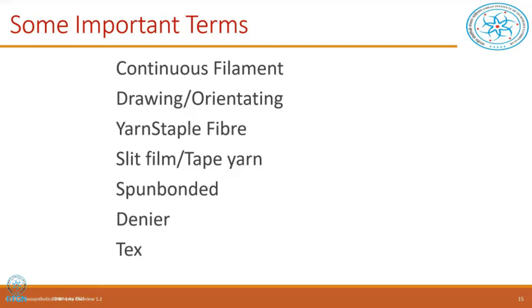So what exactly is happening with the wavy shape? This is now becoming somewhat similar to cotton. What is the difference now? The difference is that in our present system, after staple fiber, we have these elements which are cut fibers of monofilament of the same diameter and the same length. And crimping also is going to give you the same kind of crimpiness.